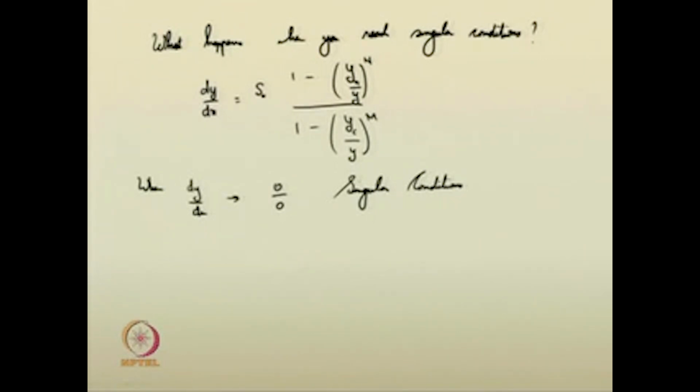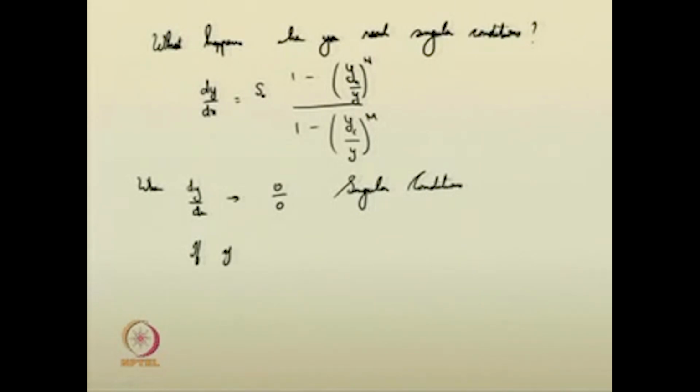So, when do you think that it becomes singular? This condition becomes singular if your actual depth y is equal to the critical depth as well as y is equal to your normal depth. When the flow depth is in this situation, then the singular condition arrives and dy by dx cannot exist. So, we have to use alternate theories, or we have to try to infer subsequent things from this.